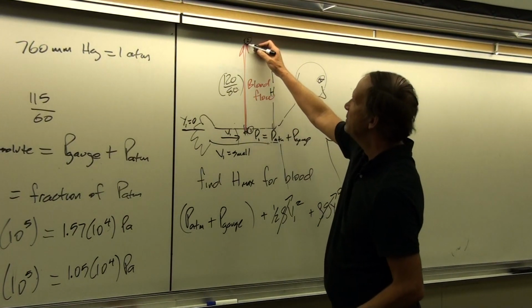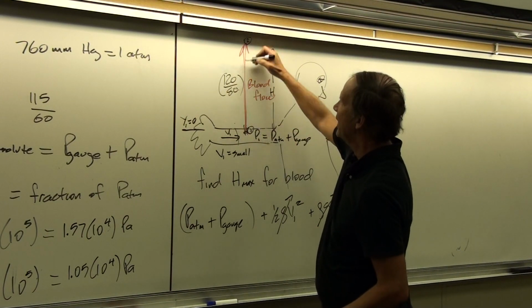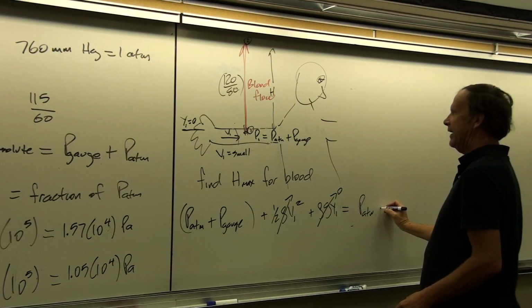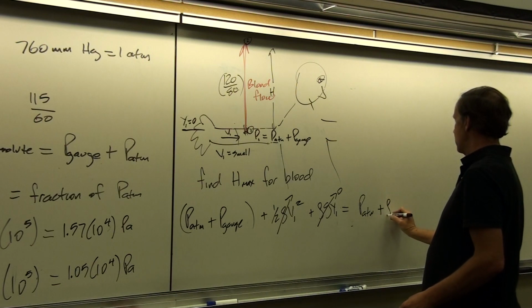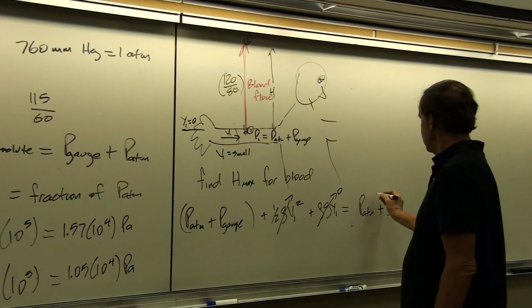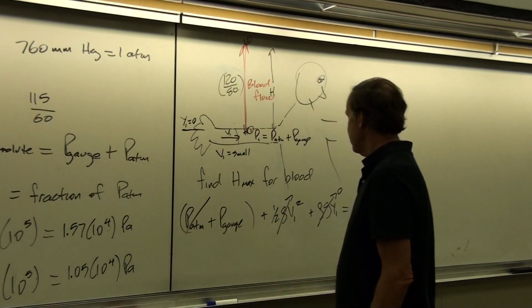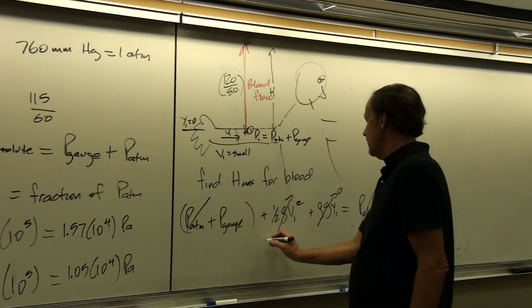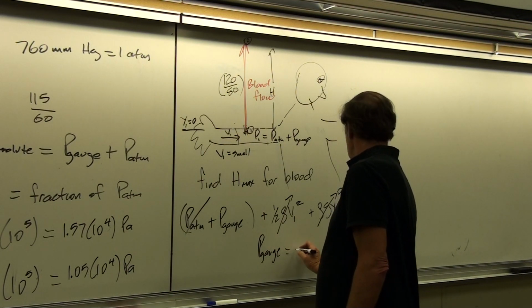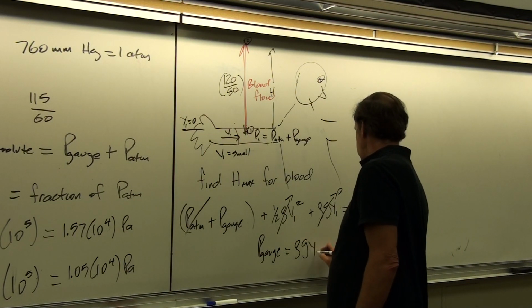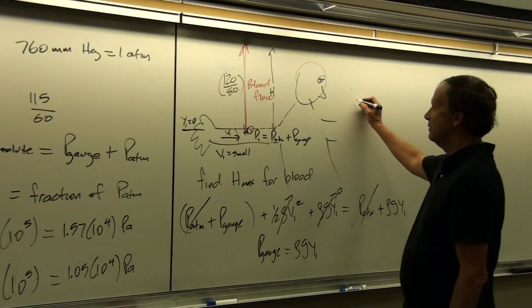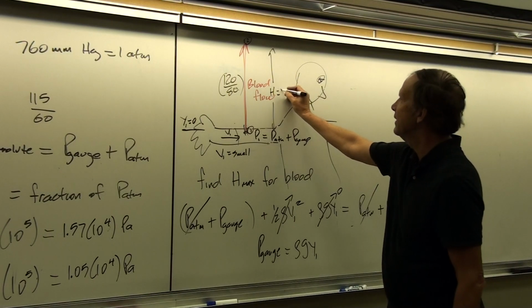The blood won't be moving at this point, so the velocity of fluid flow of the blood will be 0. And the height then will be rho g y1. Okay, so we can see here then that the P atmospheres cancel on both sides of the equation. This gives us P gauge equals rho g y1. Okay, so we can use this to solve for y1, which is our h value here.